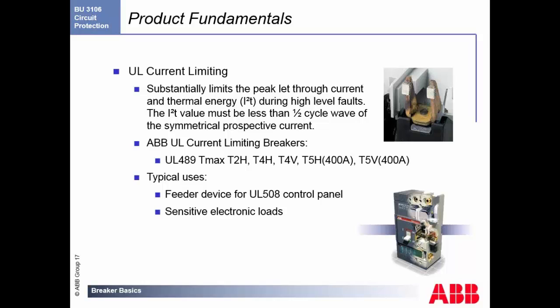So if you think about data centers or anything where a high peak or high energy, a spike in current, any kind of voltage spike, it can cause damage, which is costly, time consuming, and not the easiest to repair. Using breakers in the right way with the right settings for the trip curves, and if you do selective coordination, which is using the right breakers down the stream, you can reduce the amount of damage, the amount of downtime, and the amount of maintenance required on your equipment. Plus, you're also getting a much higher level of safety for all the people involved in maintaining that equipment.